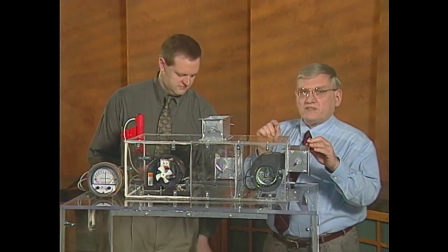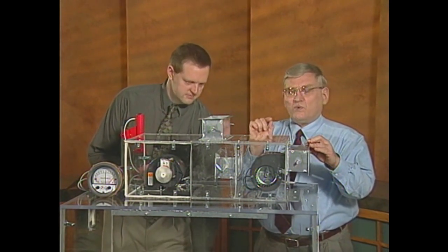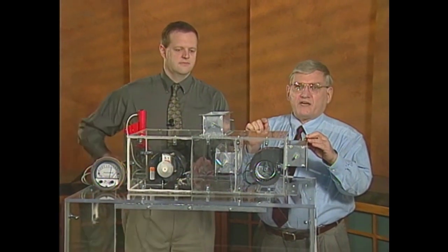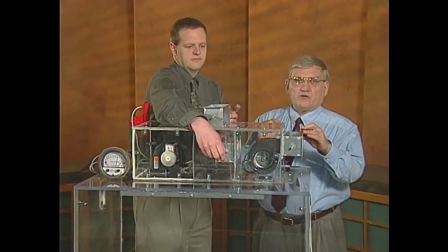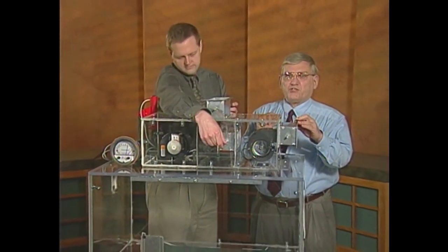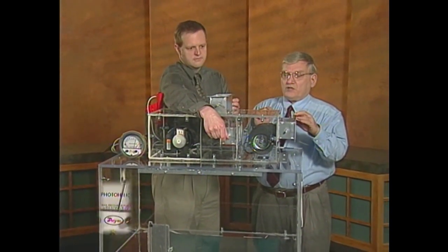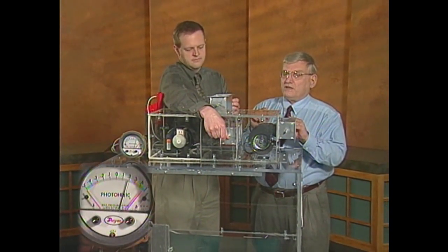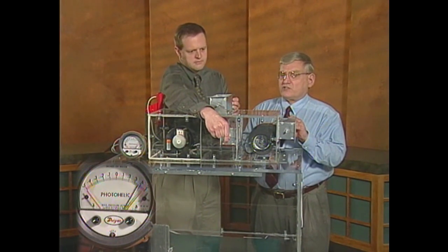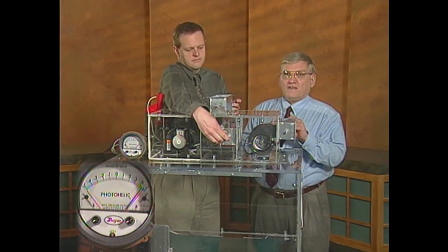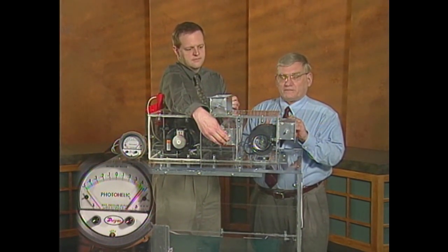Let's go ahead and turn the supply fan on with the air set at minimum outside air to the space, or in other words, a slight building pressurization. If the unit goes into the economizer mode, we'll bring on 100% outside air to the space. That increases the space pressure.